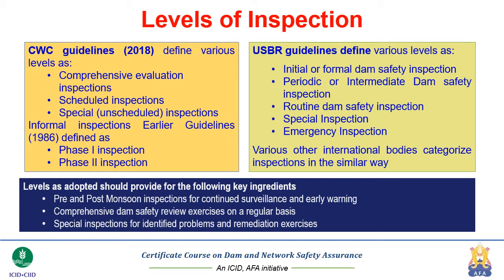period of interval, say for example about 10 years, the entire safety environment of the dam has to be re-evaluated, because the natural phenomenon data becomes available, more data becomes available. Suppose we have constructed the dam with the observation data which was restricted to about say 35 or 40 years, then after 10 years that same data length will become 50 years. Some other extreme events may have occurred during the period. Similarly, the material would have undergone some significant transformation during those 10 years because of various reasons, and comprehensive evaluation becomes necessary.